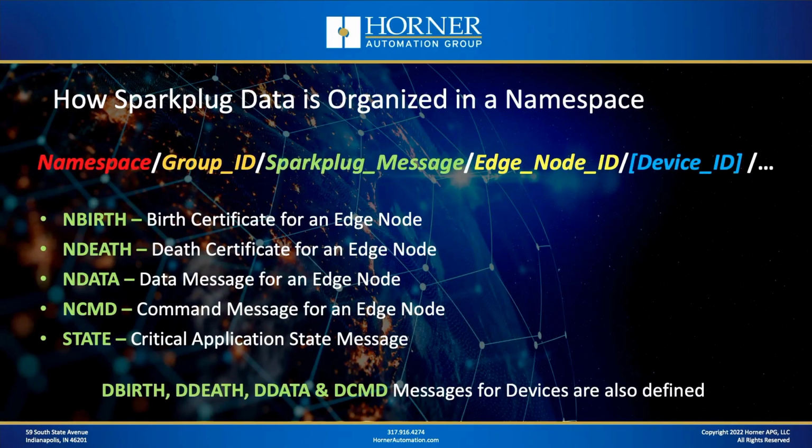And then in the middle part of that namespace there are the Sparkplug message types. And there I've got on the screen just a sampling of the Sparkplug messages. That's where you see that birth certificate we talked about, the death certificate we talked about, and data that's just being reported as routine data, could be that temperature data that I showed in my simple little example there. And that's just what you're looking at there when it comes to Sparkplug messages.